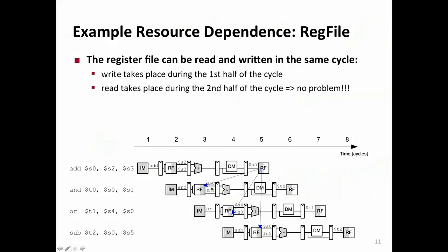And this AND is reading from the register file at cycle 3. So clearly there's a data dependency here, and this is not a correct execution order, as you can see. So you really need to somehow delay this AND until the result is available. But we will see how we ensure that this is a correct execution order, but not through the register file.